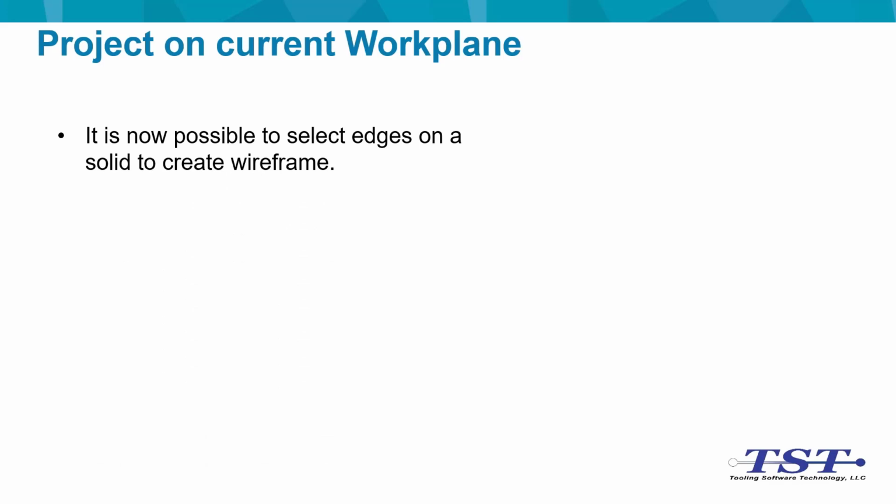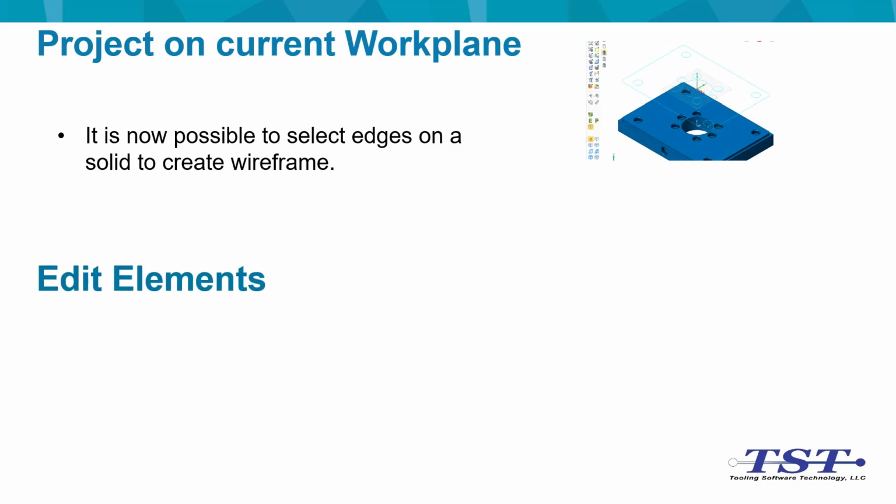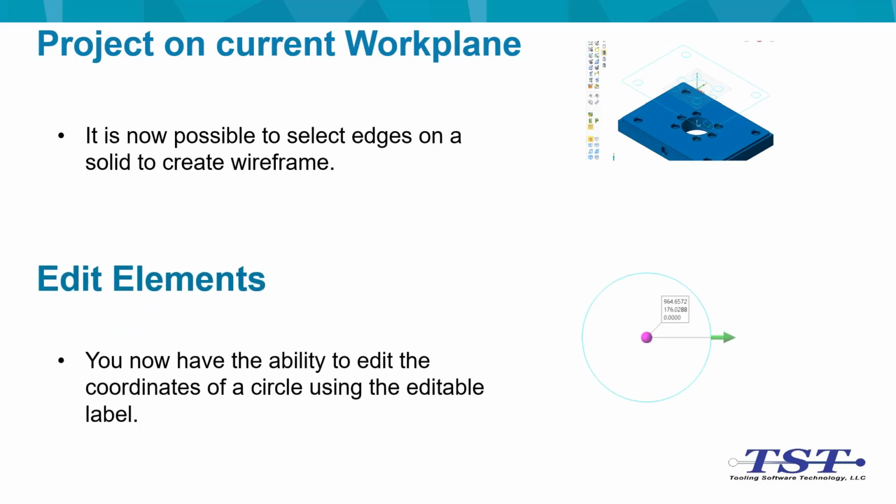With Project on Workplane, it is now possible to select edges to be able to create your wireframe squared to the workplane. And within Edit Elements, it's now possible to input in a coordinate system and type in your XYZ values for being able to translate and drag and drop from.